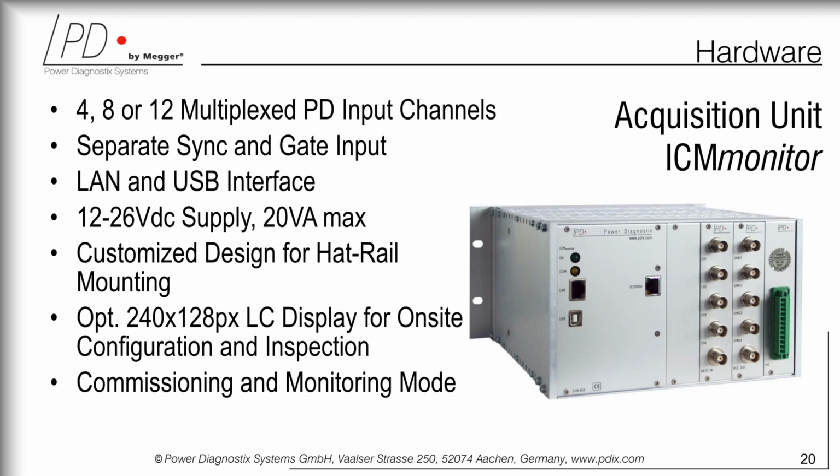And once such signals are being issued, generally a specialist is called, logs in via the LAN. Of course, this LAN port can be transferred all the way to the substation or even further into the network operation center. And there, the examination of all the patterns, PD patterns, etc., that you've seen a bit, and I will show more, takes place.